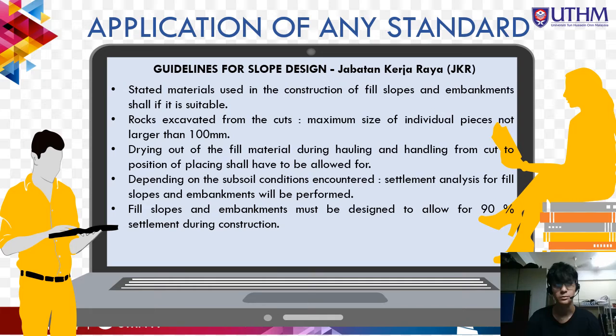I will present about the application of any standard regarding the JKR guideline for slope design. JKR stated that material used in the construction of fill slope and embankment shall, if suitable, be rock excavated from cut, with a maximum size of individual pieces not larger than 100 mm.